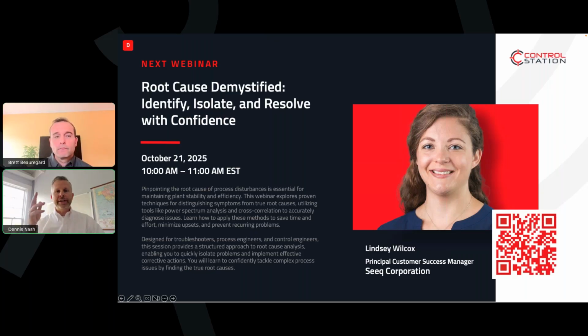Seems very fitting that we're seeing Lindsay of Seeq here as we're handling this question. Technologies, control loop performance monitoring tools like PlantESP perform that proactive analysis of a facility's continuous process data. And again, proactively is the key word here, identifies those controllers that are showing signs of degraded performance, and then ultimately characterizes the changes, whether they be an issue with tuning or loop interaction or even a mechanical issue. And again, that is something that Lindsay will dive into with Dr. Bob Rice next month. And hopefully whoever posed the question will join us for that informative webinar.